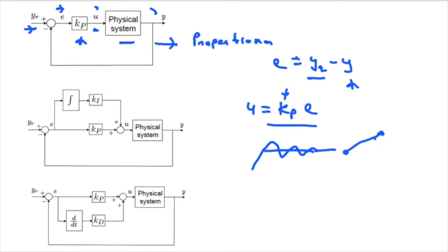Okay. So the next controller is the integral controller. There will be systems, and we can discuss that when we get to some transfer function. Let's say that's your y reference, right? Even after applying a proportional or any controller, you have some steady state errors, right? So the actual output never tracks the reference output exactly. There are small errors, 0.01 or so. But if you look at the area under this error, when you start integrating, the error accumulates, right?